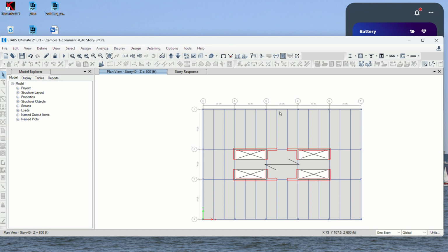So we need to move on and understand the overall stiffness, and how we can get enough stiffness by playing with the concrete strength and by increasing the wall thickness. If that's not enough, then we need to incorporate some outrigger trusses or other lateral truss elements.